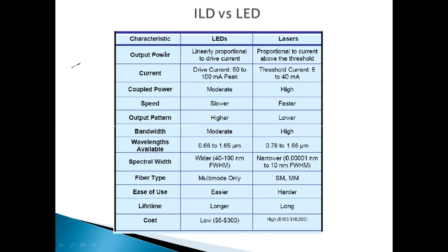We have agreed that for the laser diode, that should be the proportionality between the voltage and the current. It is linear for the case of LED, but for lasers, if you can recall, we have I and V. We have a spontaneous emission region, and then we have a stimulated emission region.